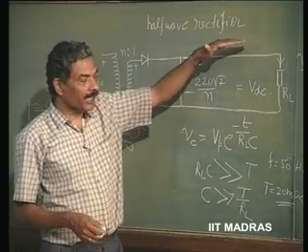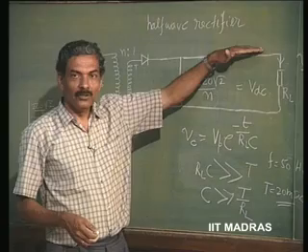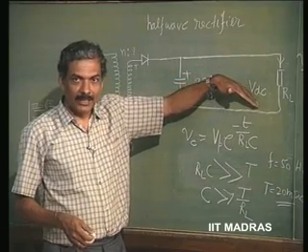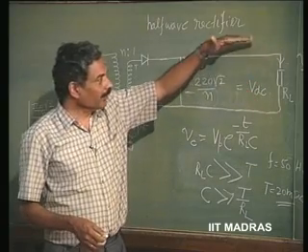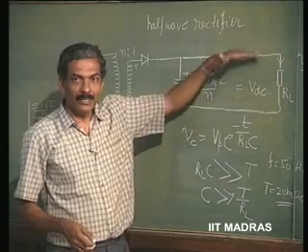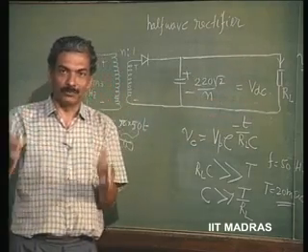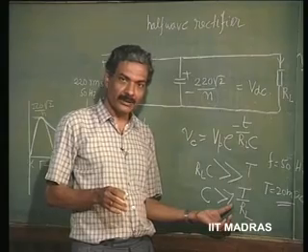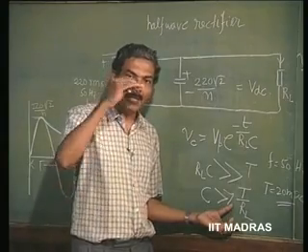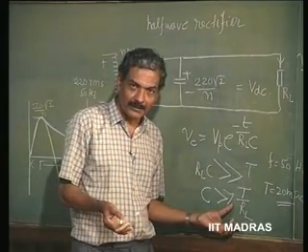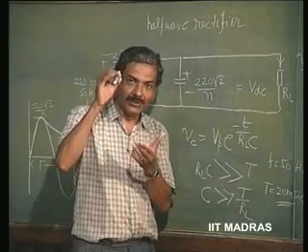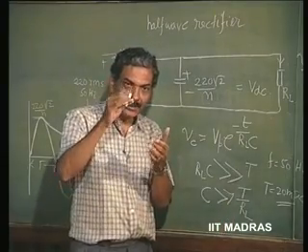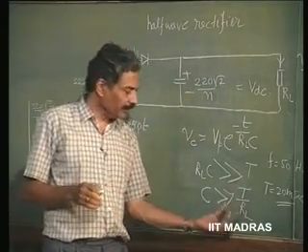If we want, on the other hand, a load of 1 ampere current to be delivered, then 12 volts divided by 1 ampere corresponds to 12 ohms. So, you can put down the value of load resistance knowing how much maximum current you would like to draw from your battery for a given voltage. So, that voltage divided by the current will give you the effective load.